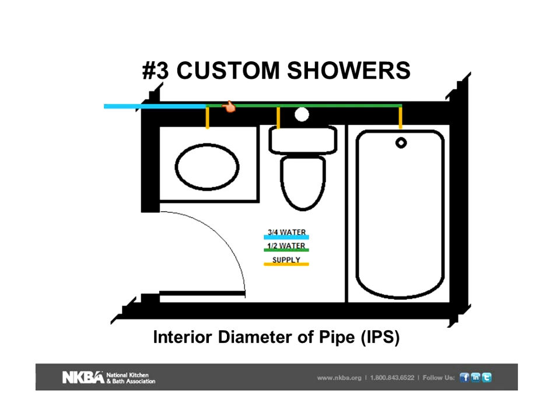I mean, after all, you may be paying the plumber per fixture. And if you're paying the plumber per fixture, they're doing all the rough-in. They're paying for the rough-in material. Then they'll come back and do the final connection of everything once all of the wall material is up. So if they're paying for the material, changing from a 3/4 inch water line to a 1/2 inch water line doesn't sound like a big deal, but day in and day out, 3 bathrooms in one house and a kitchen, you're going to save a little bit of money by reducing that pipe size.